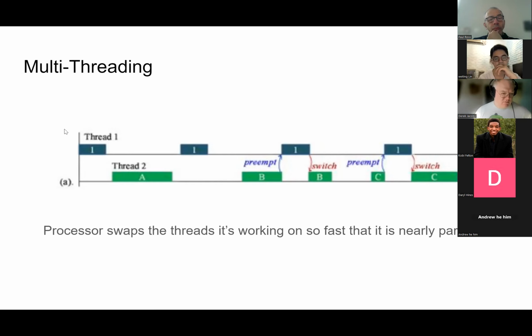Great, now I have thread 1 that measures my temperature and thread 2 that does the sending. In a multi-threaded process, the first thing will get worked on, and if that work finishes, great, and then the sending can happen. And when that finishes, great, and then it'll measure again. Say here in block B, if we started to send off that data, but you wanted to take another measurement, then the meta process can figure out, oh, stop trying to send the data for a second because I have to take this measurement. In that way, you can keep the real-time behavior, because the processes that need to happen exactly when they need to happen can. So you can break up your calculations like this.